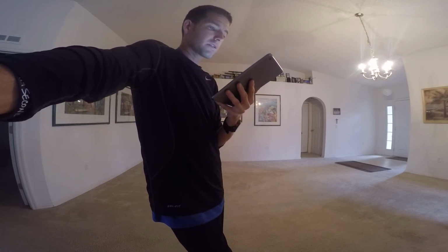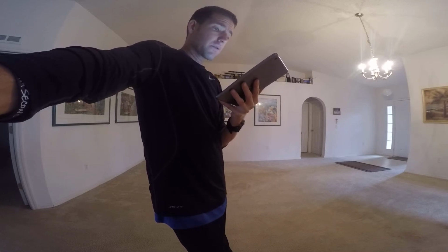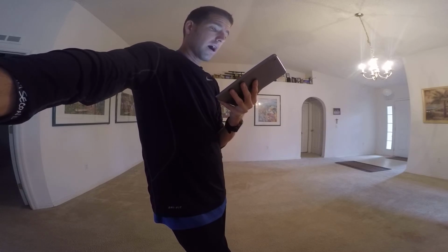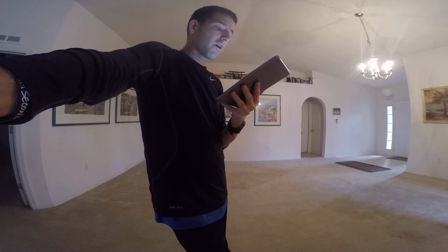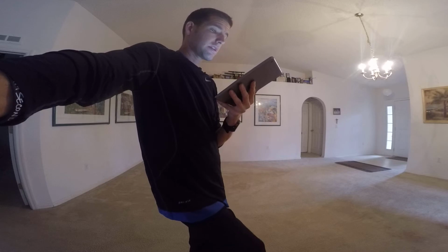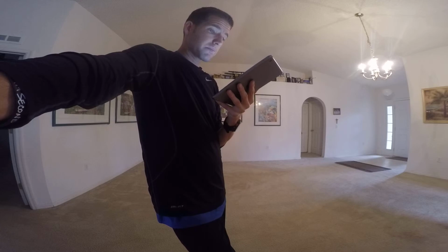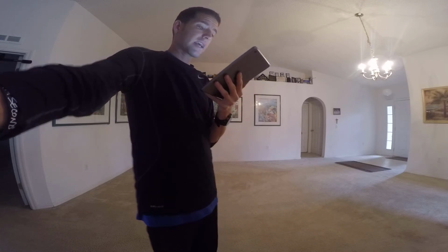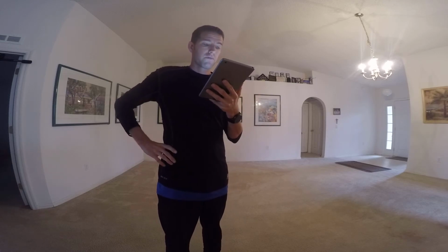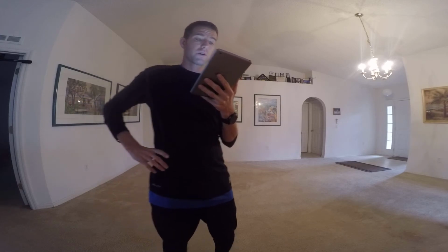Blade flapping compensates for dissymmetry of lift in the following way. At a hover, equal lift is produced around the rotor system with equal pitch, angle of incidence, on all the blades and at all points in the rotor system, disregarding compensation for translating tendency. The rotor disc is parallel to the horizon. To develop a thrust force, the rotor system must be tilted in the desired direction of movement. Cyclic feathering changes the angle of incidence differentially around the rotor system. Forward cyclic movements decrease the angle of incidence at one part of the rotor system while increasing the angle in another part.